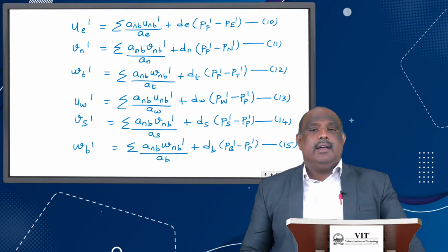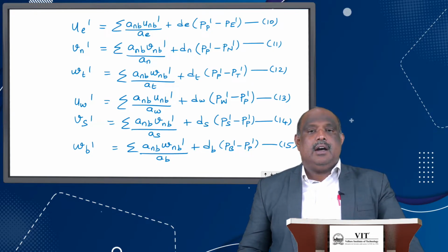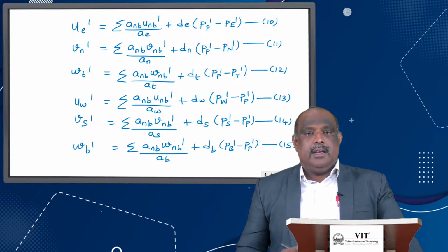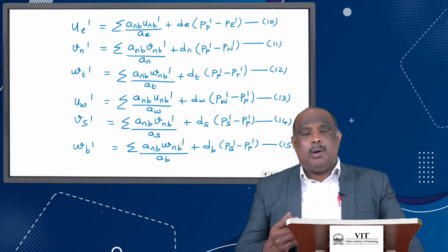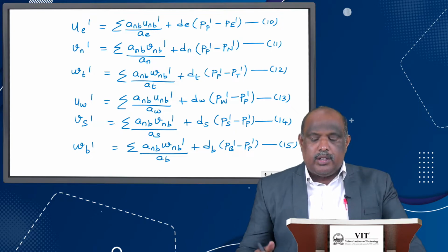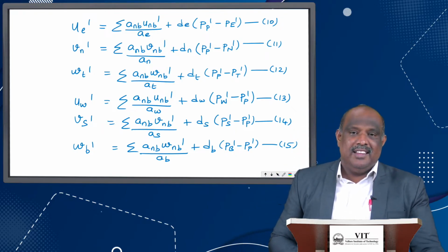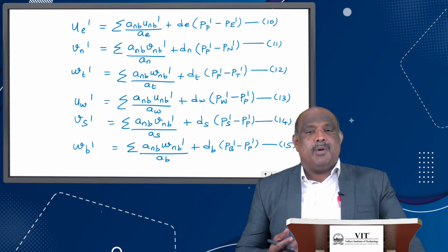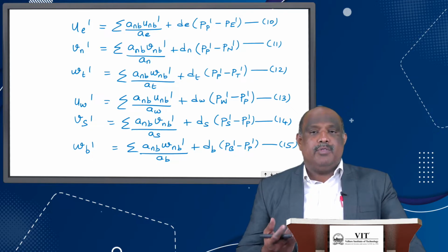So now you got the equations for the velocity corrections along the x direction, y direction as well as the z direction, in both right and left, front and back, top and bottom. So we got these 6 equations. Now my question is whether our problem is solved. What is our problem? Our problem is to find u, v, w and p from the momentum equation. We have only 3 equations, but there are 4 unknowns.